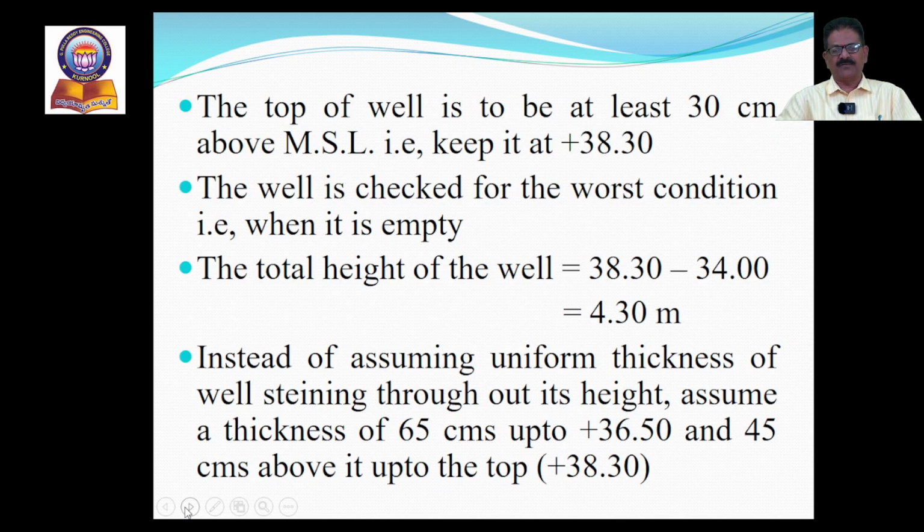We can refer to the same figure for the entire description and the design of this component. The top of the well is to be at least 30 centimeters above maximum water level. Therefore, we should keep it at plus 38.30 meters. And the well is checked for the worst condition. Obviously, for the design purpose, the critical or worst condition is when the well is empty. There is no water in the well, let us imagine. So the well is empty.